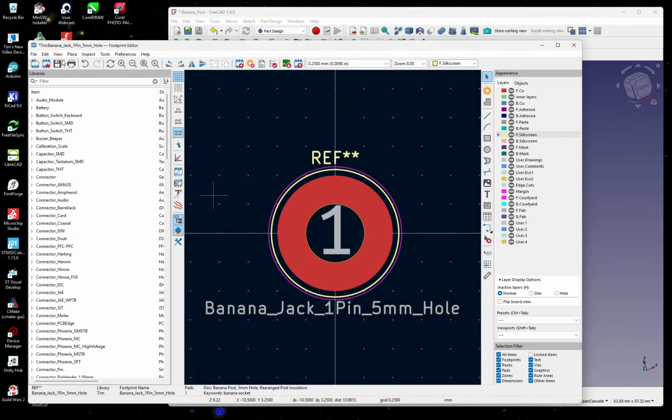So I've closed the editor, and we bring up our PCB. Nothing's changed on here. If we go look on the 3D model, nothing's changed. What we need to do is actually update this from what we've actually done. So if we go to tools and we go update footprints from library, and we do that update, and it's updated that one there, you can see. Close. So now it doesn't look any different because this is just PCB. You only get one view on a PCB. But if we look at the 3D model, we should now see that it now shows our thing in there.